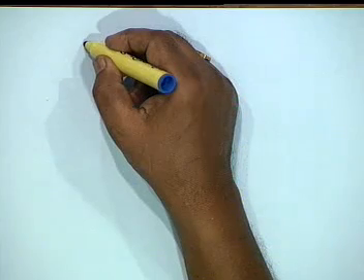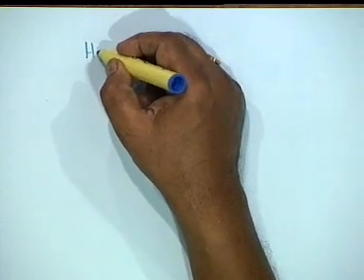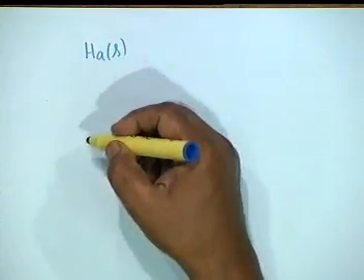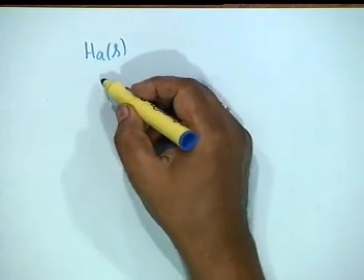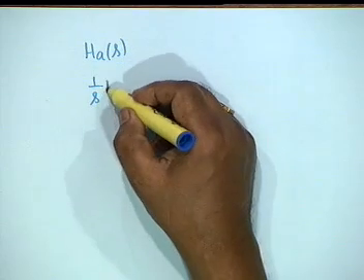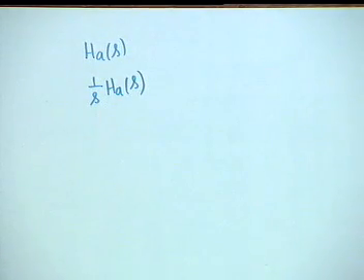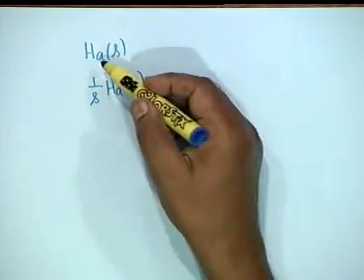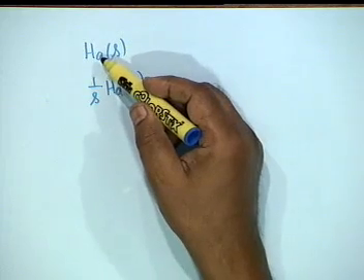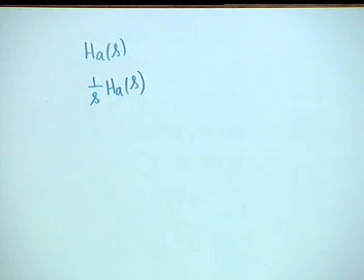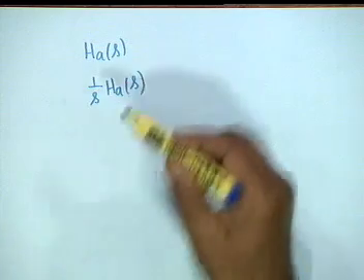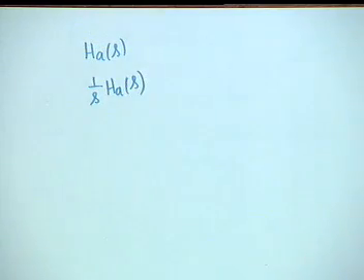One is derived in the usual manner, that is, starting from the analog filter. What is the step response? The unit impulse response in the frequency domain is HA of S. The Laplace transform of the unit step response is HA of S multiplied by 1 by S.